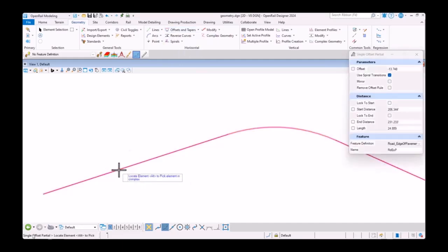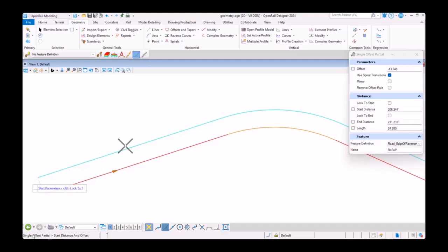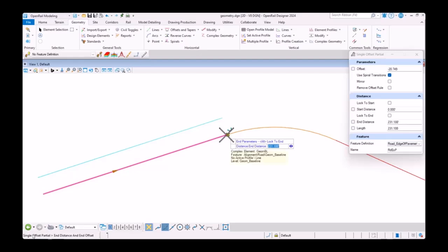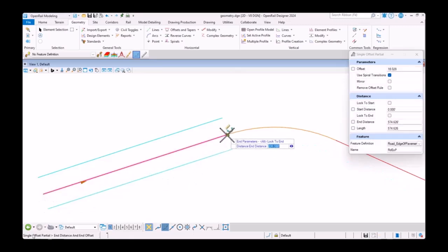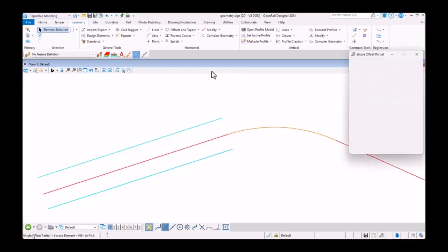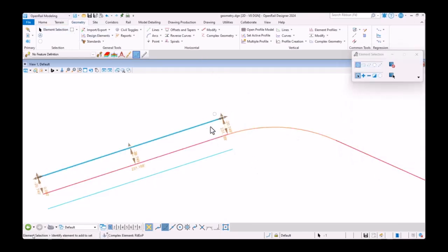Let's take a look at this as an example. We'll do an offset geometry here. We'll turn persist off first and snap to the end of this tangent. We see our snap icon in there, the key point snap in this case. It will snap to there, but it is not being persisted. Now let's turn persist on. We'll place another one on the right-hand side of this geometry, and notice that we get immediate feedback, and just by looking at the screen, I know that I'm persisting that.